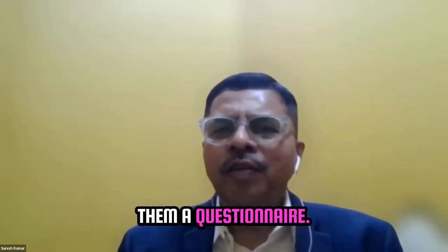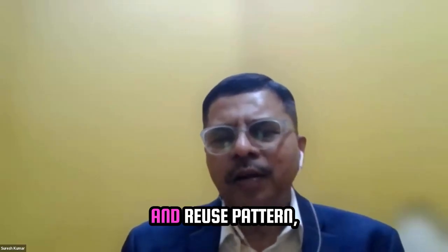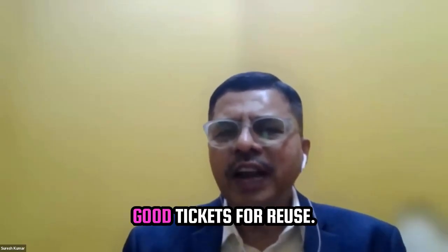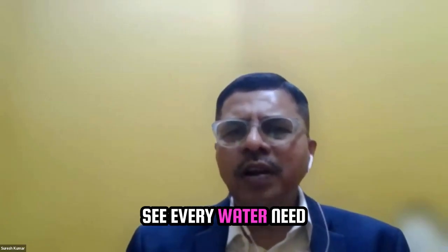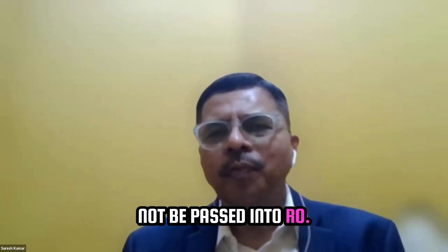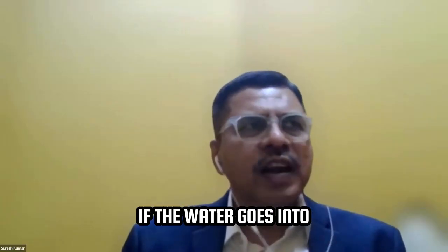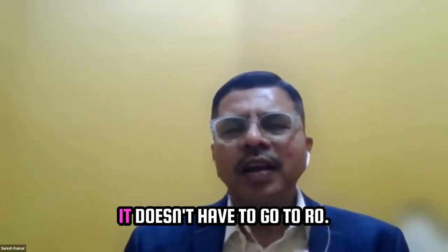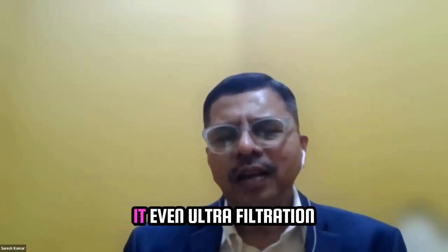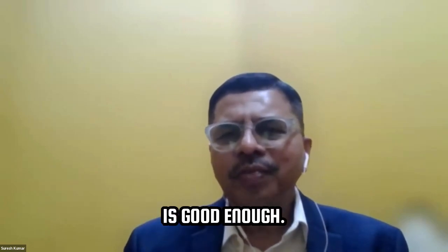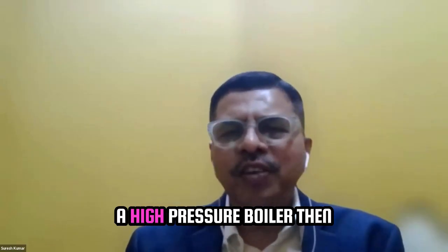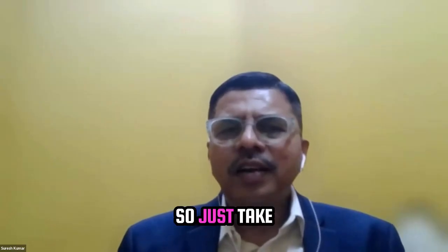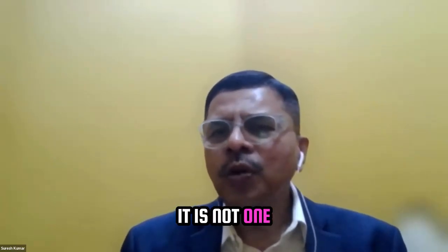Maybe you can just send them a questionnaire. What is your source of water and reuse pattern? How would you like to reuse? What are the quality requirements for reuse? See, every water need not be passed into RO. If the water goes into, let us say, a cooling tower, for HVAC requirement, or boiler feed, it doesn't have to go to RO. Even ultrafiltration is good enough. Or if the boiler is a high pressure boiler, then you have a case for RO. So just take a selective approach. It is not one solution fits all.